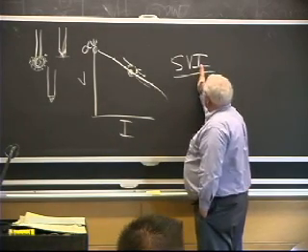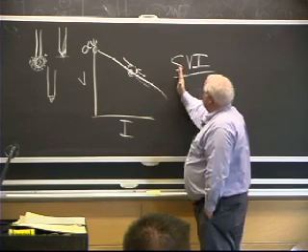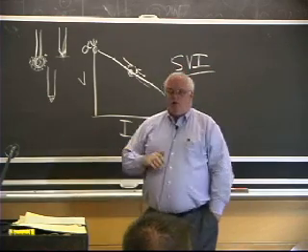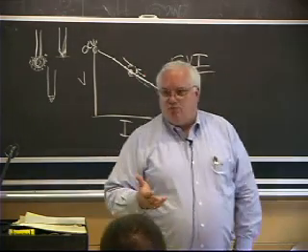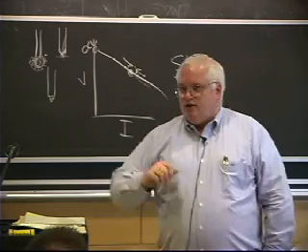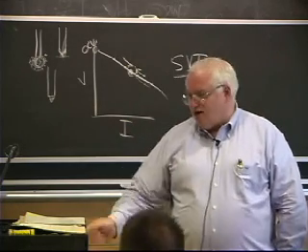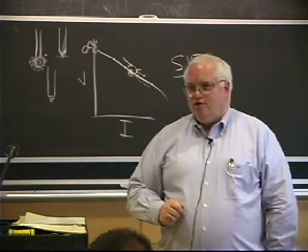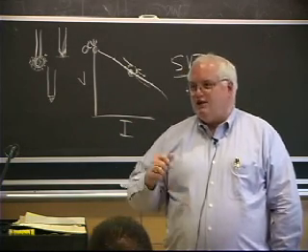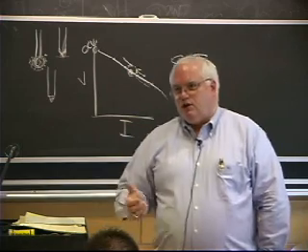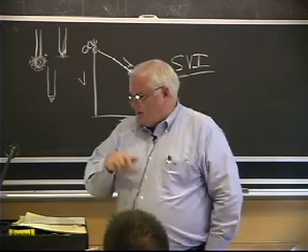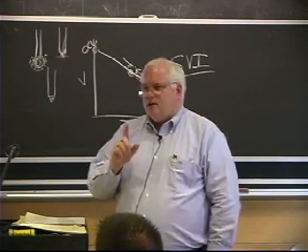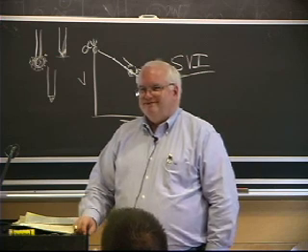So you're dampening the system here, and the slope is providing your self-regulation, and the voltage is controlling the power. So there's a lot of stuff in welding power supplies. You can't just plug into 110 volts and strike an arc and weld with 110 volts, okay? Because there's nothing to control and self-regulate the circuit, okay? So anyway, that probably more than answers your question, right?